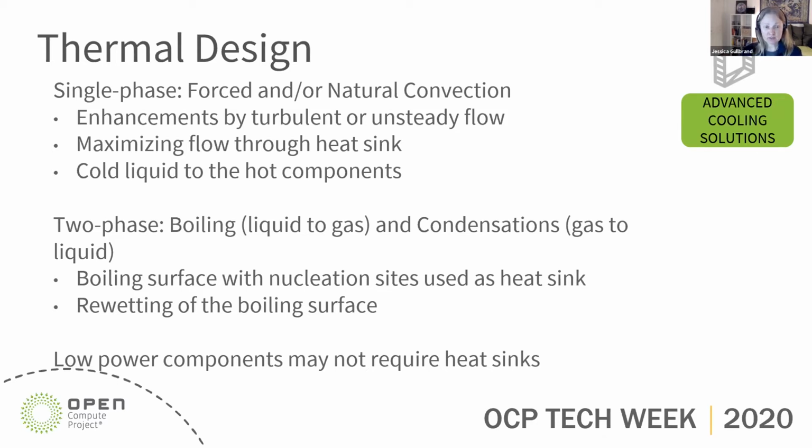Here you're not necessarily having a heat sink, but a different type, or a simplified heat sink, which is really a boiling surface with nucleation sites. So you want to make sure that you're creating as many nucleation sites as possible in order to get as optimal cooling capability as possible.